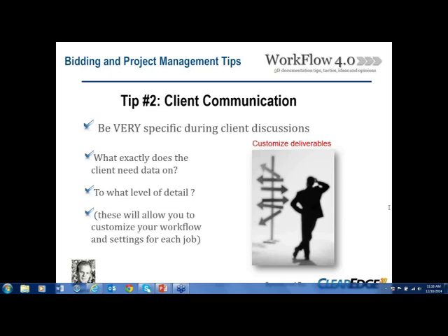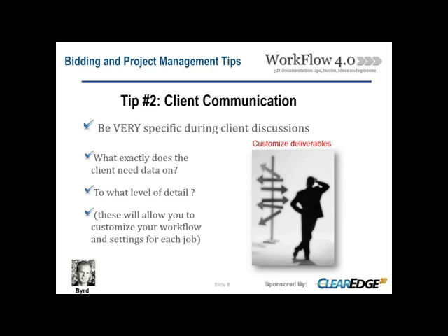So be very specific on what exact items your client needs and what level of detail, because those will allow you to customize your workflow depending on what it is that you actually need to pick up on site. And that can also change, you know, you may go from a 1-week project to a 5-week project depending on how much detail is needed. Do you need to get up in ceiling tiles? Are you looking to model 1/2-inch electrical lines? Knowing those things is very critical during your planning.